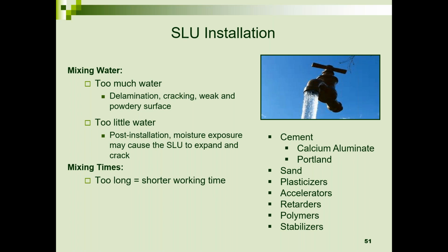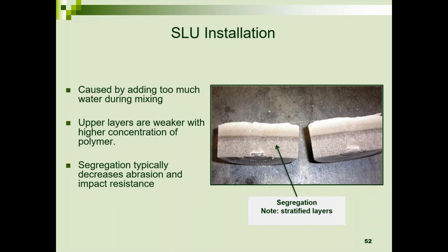Working time is affected by how long you mix it. More is not better. If you mix an excessive amount of time, you're going to be eating into your working time with that product. If you don't mix enough, again, your flow and heal rate may be affected, as well as the chemistry on the right may be impacted. So again, the amount of water you add, how long you mix it, and how well you control the environment, meaning temperature, wind, sunlight, humidity, that's very important to understand before you start your project.